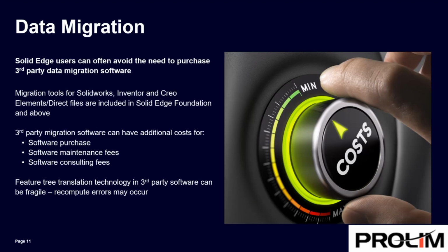So one thing about third-party migration software, there's additional costs, right? We have software purchases, we have software maintenance fees, and then software consulting fees. And then hopefully it's compatible with where we're going to where we've been. And then the feature tree translation technology in third-party software can be quite fragile in my experience, and recompute errors often occur. So there's always kind of a risk in using these non-direct CAD third-party migration tools.